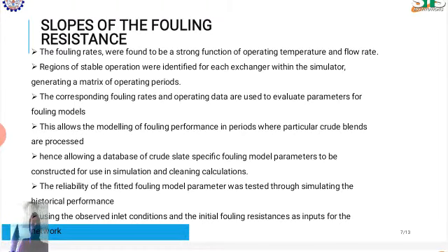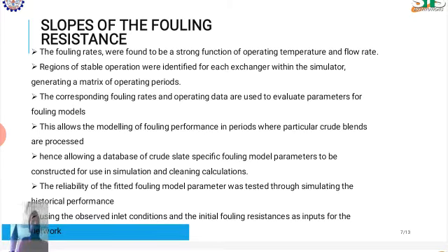Therefore, the fouling model together with the crude thermodynamic data, network simulation model and furnace model was able to predict the historical plant behavior. Simulation studies of the future performance are now executed to evaluate the best methodology to manage fouling in the PHT.